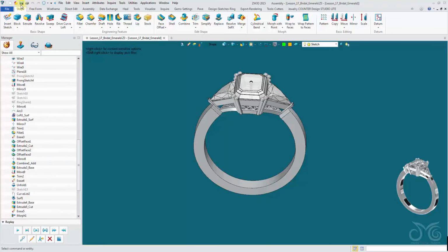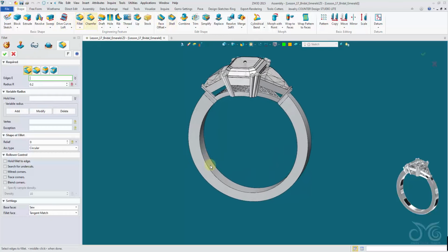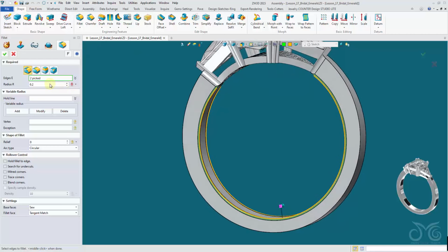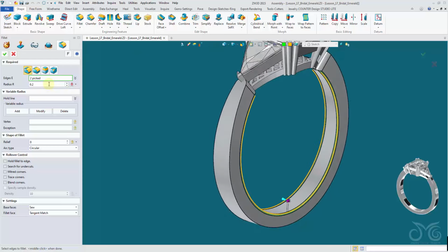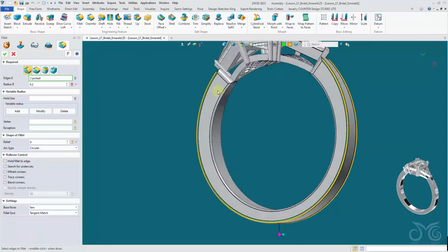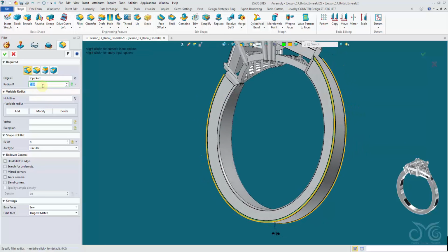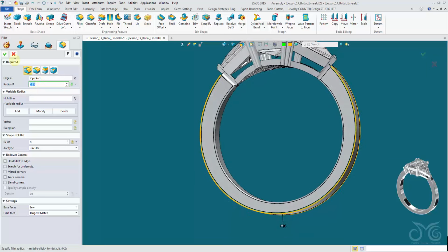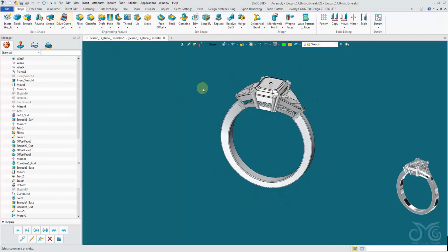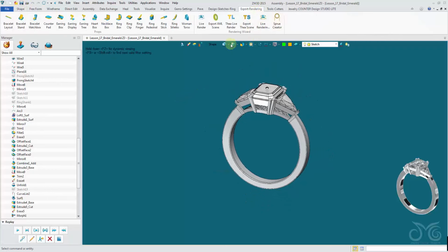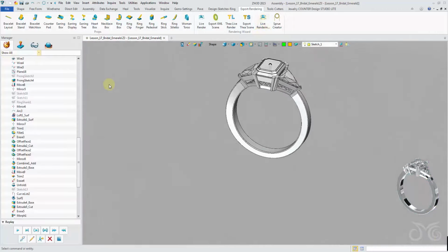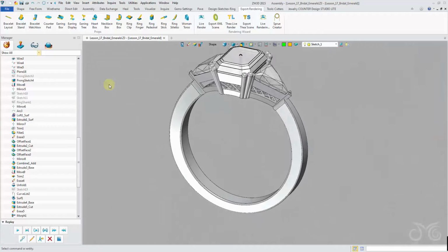Let's save again. Okay, I'm going to add in another fillet, both for rendering and maybe for comfort fit purposes. So I'll add in fillet in here. 0.2 is good. Middle click, and up here. Slightly less. Okay, so we'll save. Export and rendering. Live rendering studio. Confirm to place it. Okay, and we'll just use the free live renderer.